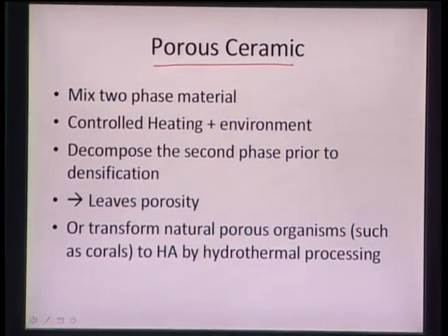Then after we have consolidated it, we have densified it, we will basically polish it to our finished size. And in the second case, we can also achieve something called porous ceramics. And in porous ceramics, how do we get it? First of all, we will mix a two-phase material, and we provide controlled heating with a controlled environment.